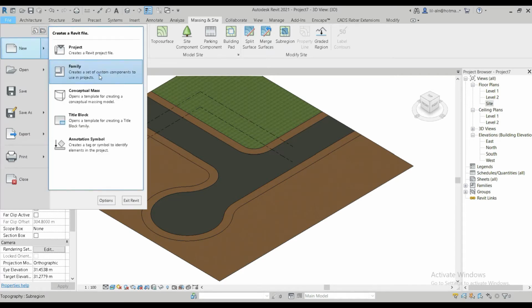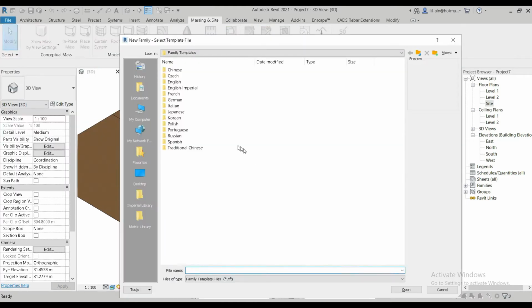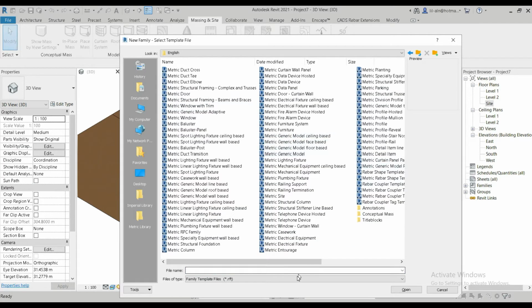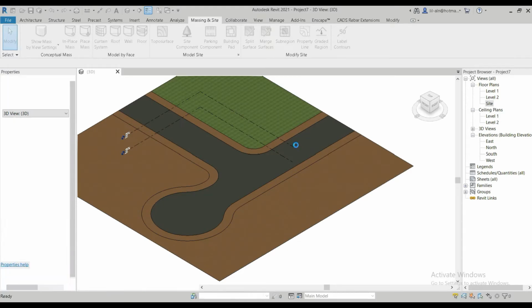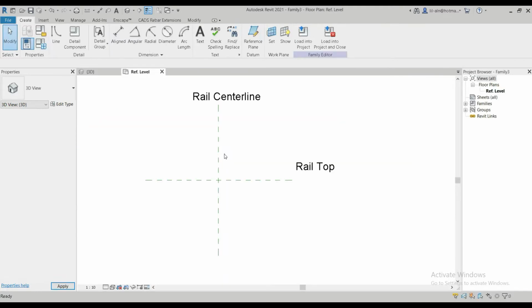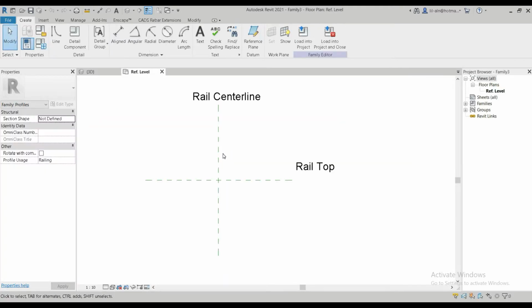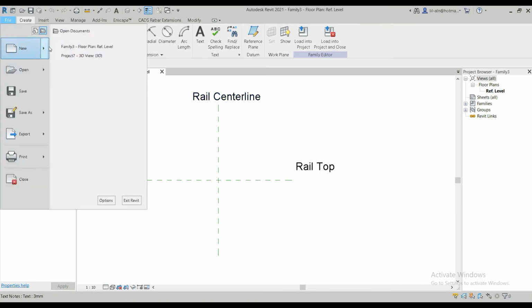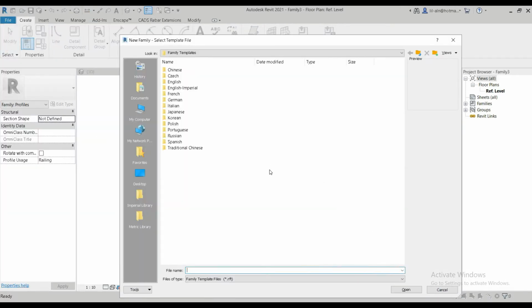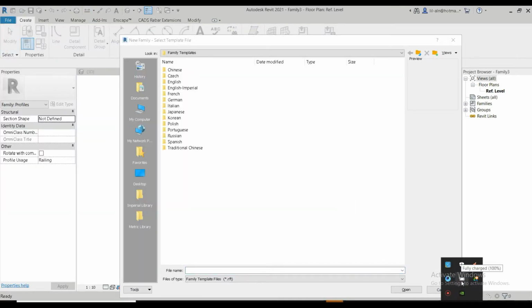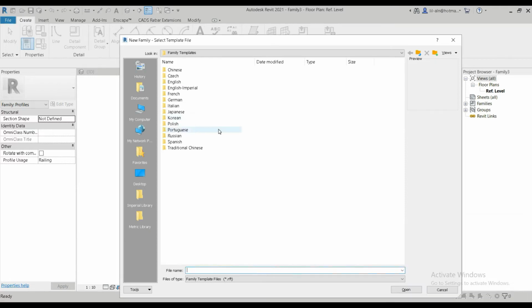So now, when it comes to creating roads and curbs, there are a few different ways of doing it. In this video, I'm using the rail method, right? Which is very important for you to make clear. I'm using the rail method. So we're going to make two separate generic families, and then we're going to use a rail, and we're going to load those families inside that rail, right? So the first thing is making two families. One is going to be the footpath or the sidewalk, and the other one is going to be the main curb.